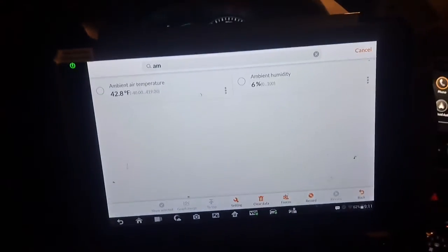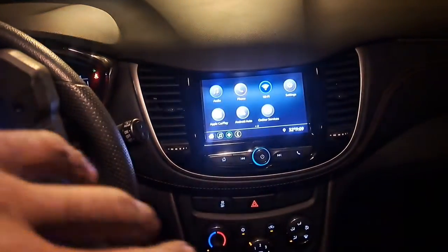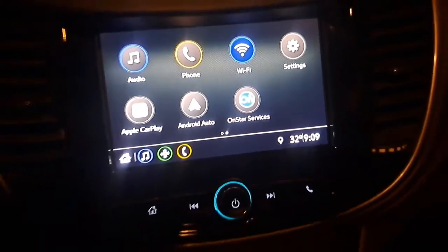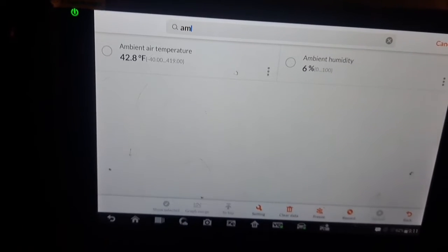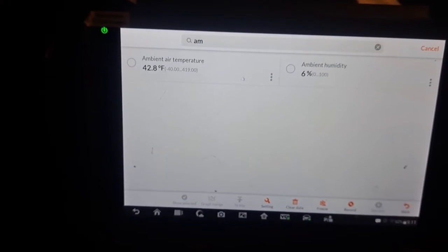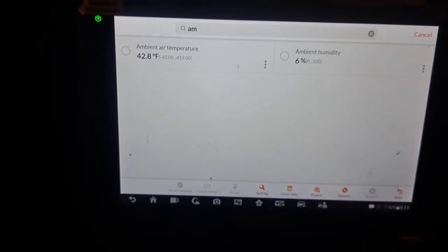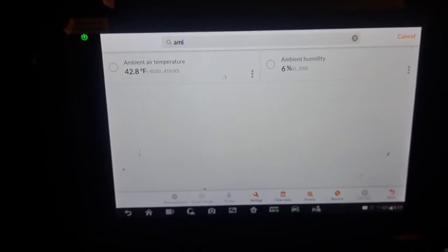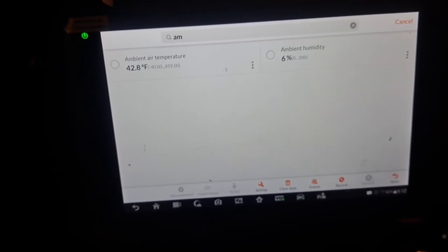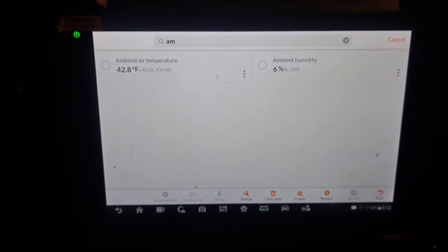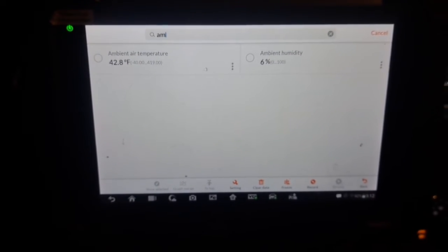All right, just came on my test drive a while ago. The temperature on the monitor dropped to 32. It's hovering around there. It's not 32 degrees out here. Temperature in the PCM is at 42 degrees, and it's like 70s right now. So I'm not understanding why it's doing that, but it is slightly rising. Maybe after a while of driving it, some things will change. Maybe it's a programming thing. The service information didn't say anything about having to program it. I'd imagine it'll automatically recalibrate.